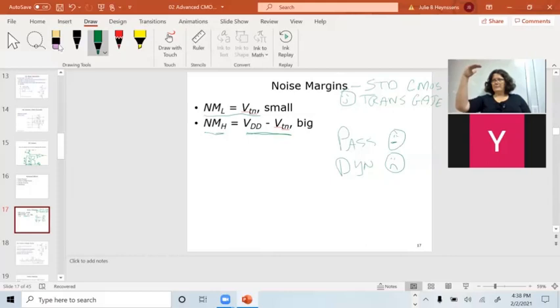I have a memory, and you have a 2D array of memory cells, and I have a row drive circuit that I have to fit in whatever the size of the memory cell is, which is really small, because I'm going to have to put another one in the next row next to it. So I got to stack them.